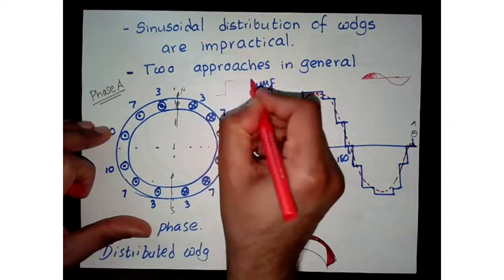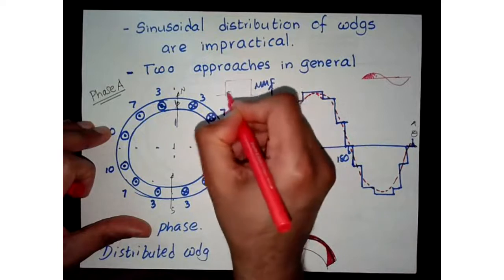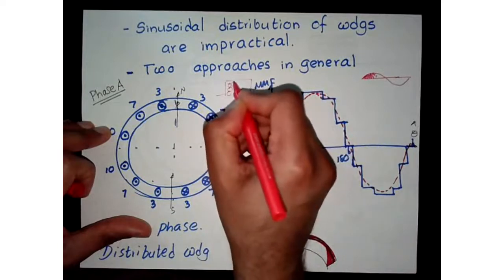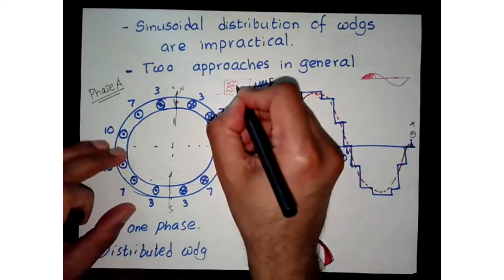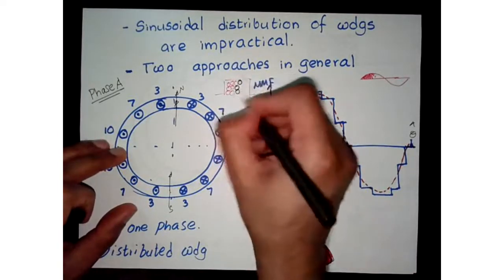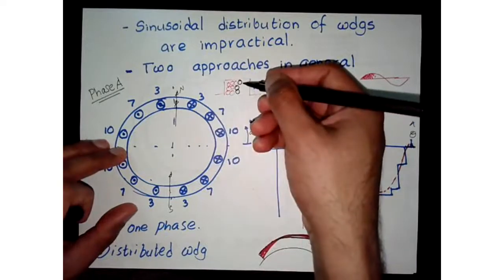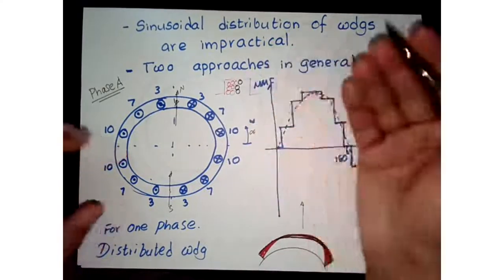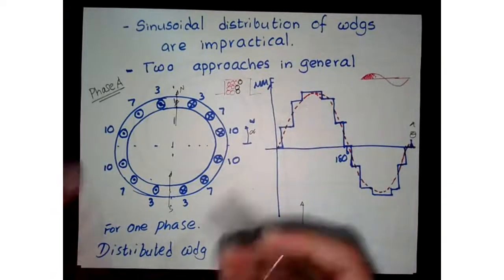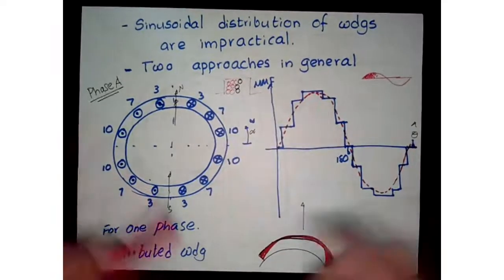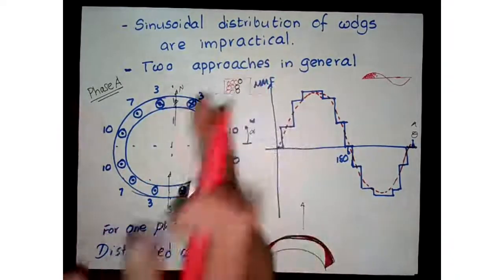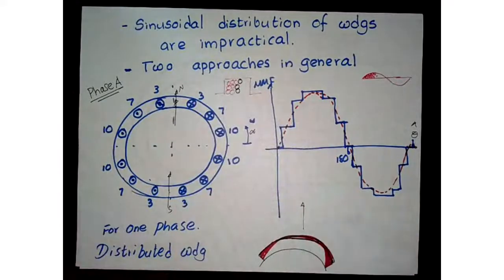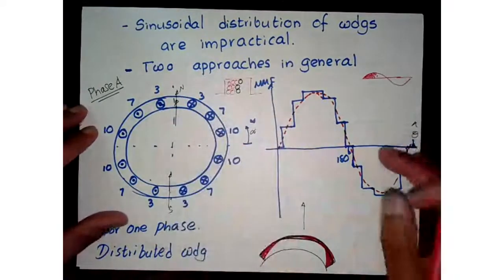Let me draw a cross section. So I have, let's say, 2, 3, 4, 5, 6, 7 of phase A, and then let's say 3 of phase B. I'm just choosing a random one. So 3 of phase B, and then 10 of phase C, right? So you can have such a combination in that single slot, where as you go around the rotor, you see the different phase A, B, C winding ratio change, but you are using the same number of slots.